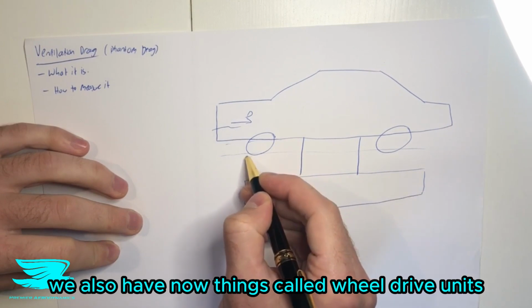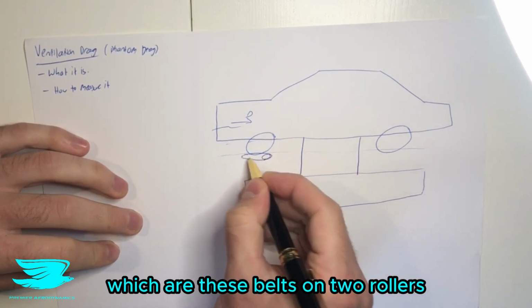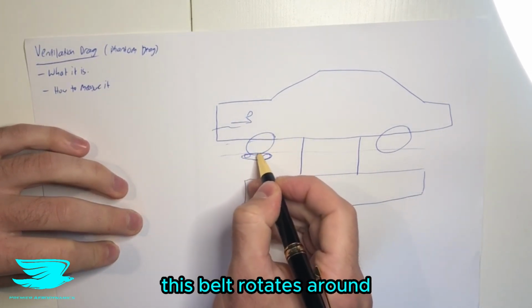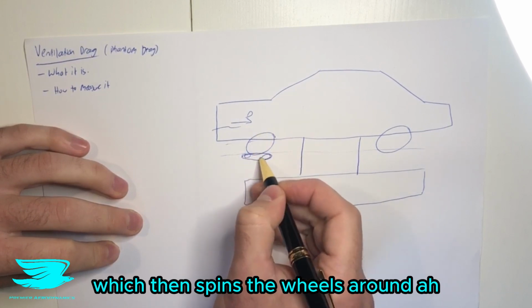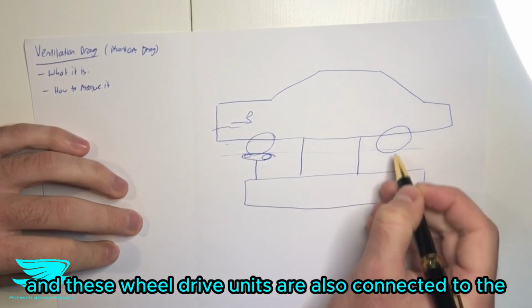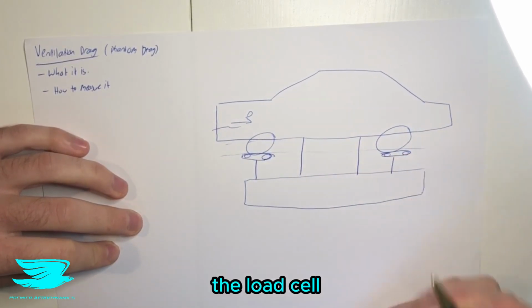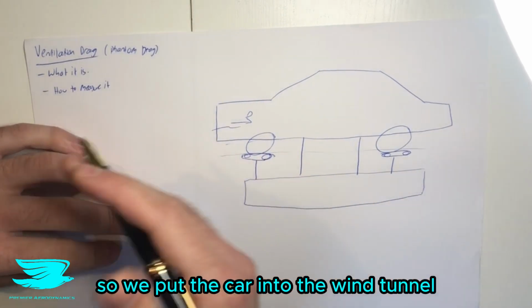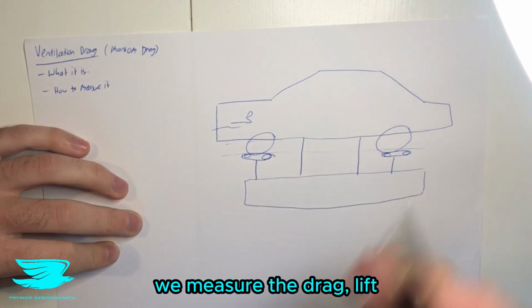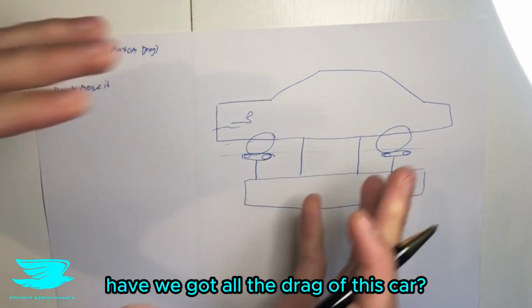We also have now things called wheel drive units, which are these belts on two rollers, or however many rollers you want, and this spins the wheels. This belt rotates around, which then spins the wheels around, this way, and then the wheels spin that way. And these wheel drive units are also connected to the load balance as well, the load cell. So we put the car into the wind tunnel, we run the air, we measure the drag, lift, side force, moments.